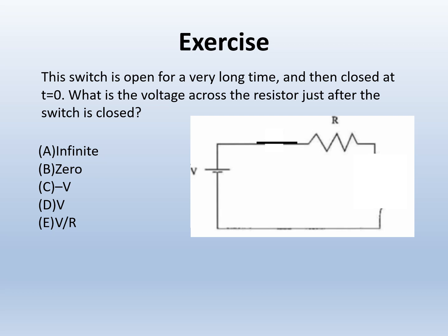And that magnetic flux was not there before, so the inductor says, no, I don't want this. So the inductor induces a voltage to completely cancel the new current, so that it can go back to the zero flux condition. When the inductor does that, the current through the loop stops.